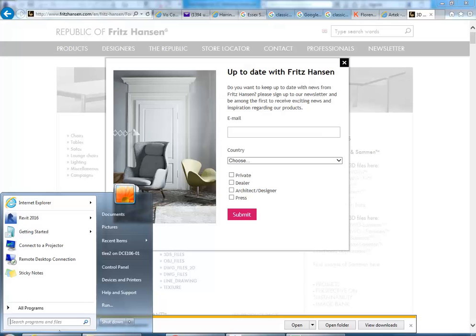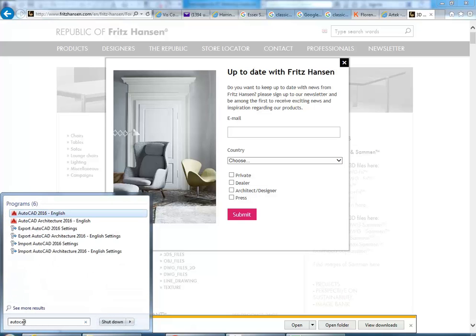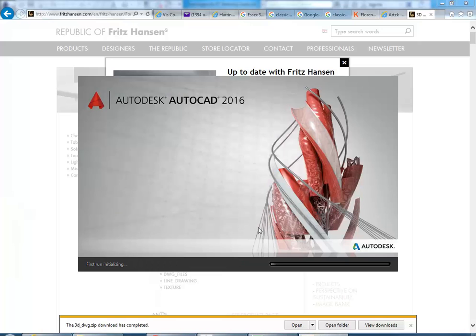So you can try just bringing that straight into Revit. You just open it, but I'm going to have a look in AutoCAD. Because we've got AutoCAD, we may as well have a look at it and see what's there. And then you sometimes need to make changes as well. You can do all of that in AutoCAD, because once you bring it into Revit, it's very difficult to make changes other than changing materials and those kinds of things.